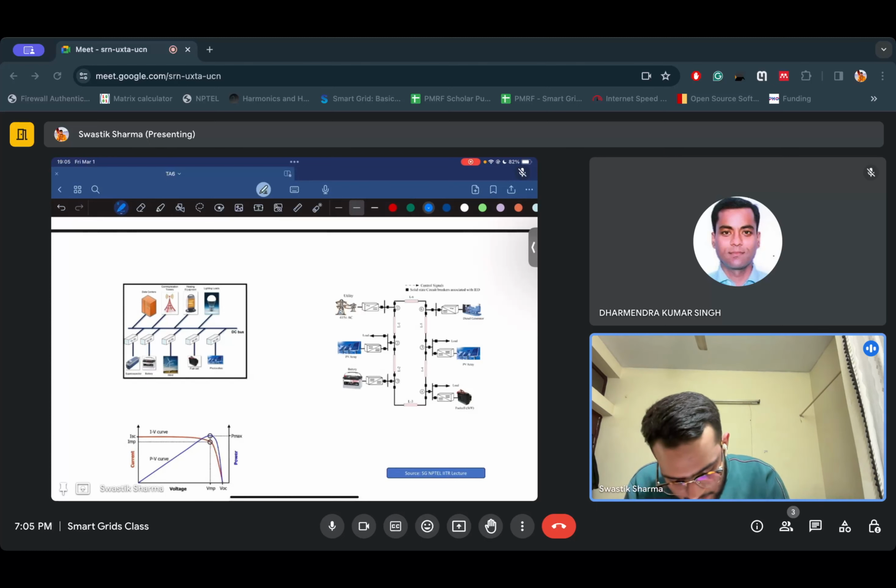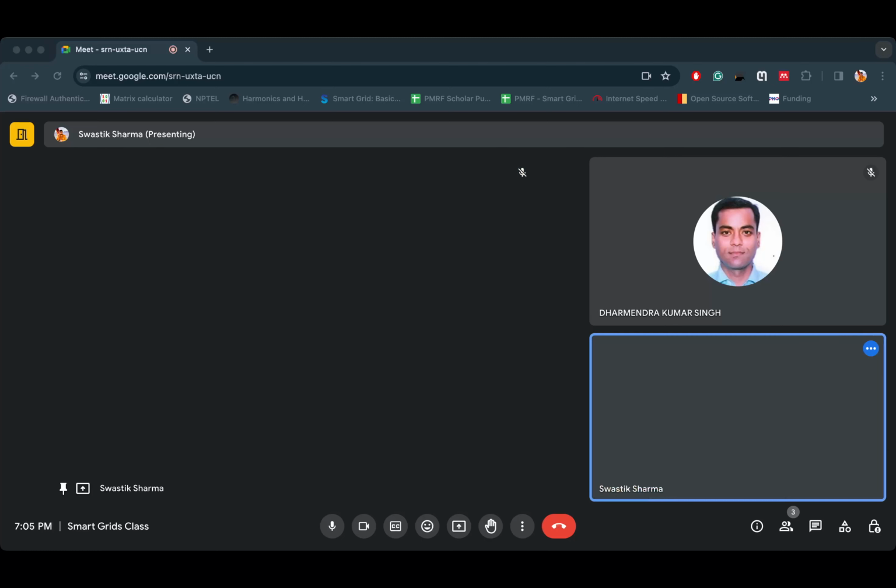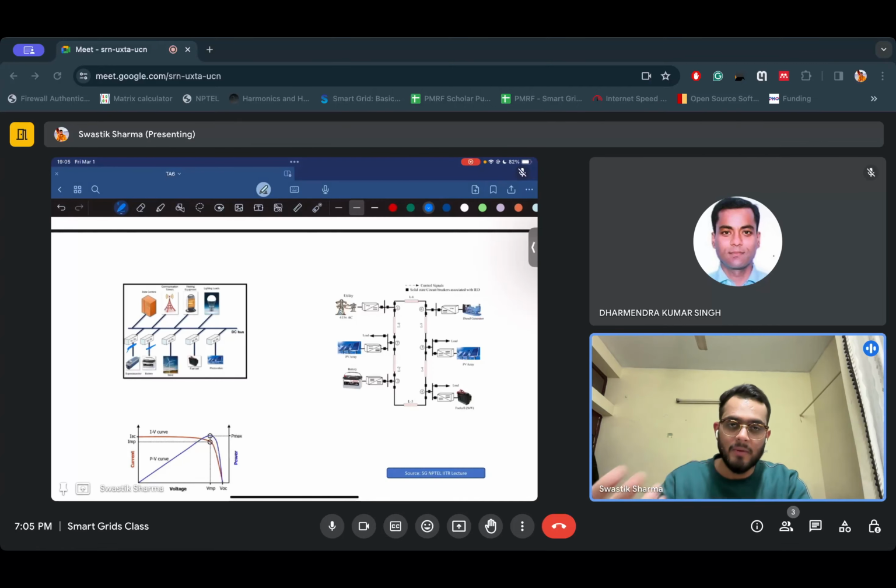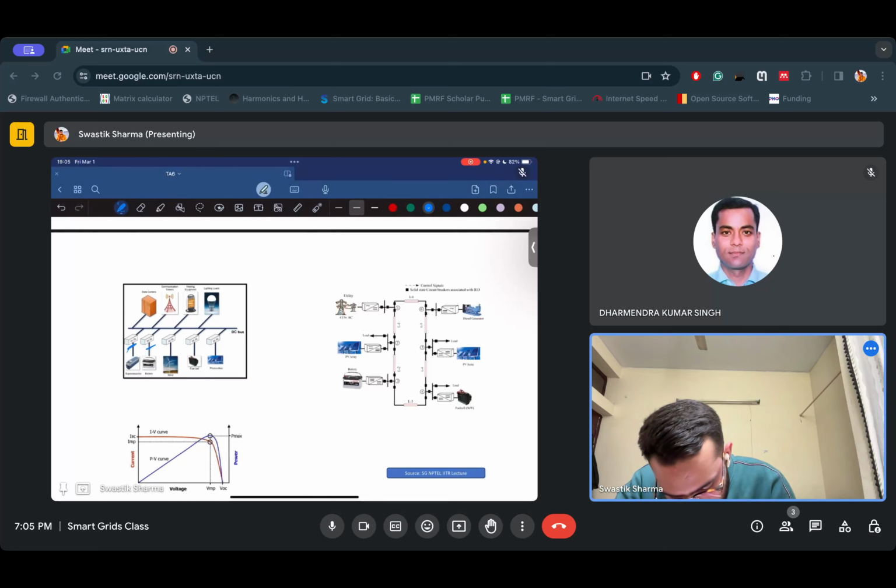So like you see in this first diagram, you'll see that supercapacitor, battery, wind, fuel cell, photovoltaic, all of them can be connected using converters. This supercapacitor will require only a DC to DC converter because it supplies power in DC. Then battery is also DC. Wind generally has a turbine connected to synchronous alternators, so there you need to convert it to DC first. Fuel cell supplies power in DC and photovoltaic supplies power in DC. And your data centers are all DC in nature. Your communication towers are DC in nature. Heating equipment and lighting loads are all DC.